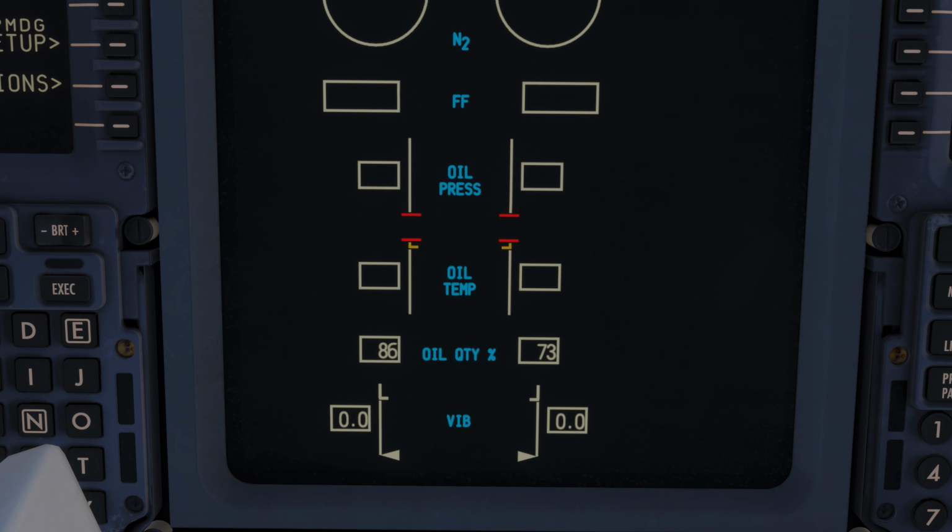But the same applies the other way around. If the oil pressure is too low, then there is not enough pressure to keep the rotating metallic parts away from one another, and therefore they might touch one another, which in turn is going to lead to damages. Therefore, the oil pressure tells us something about the condition of our engine. If the oil pressure is too high, we know that we got a problem. If the oil pressure is too low, we risk getting a problem because rotating metallic parts may touch one another.